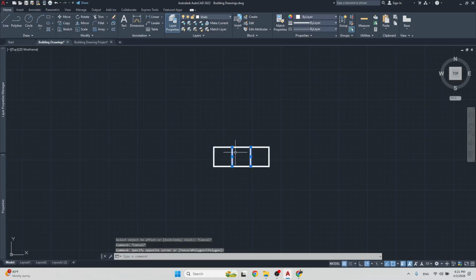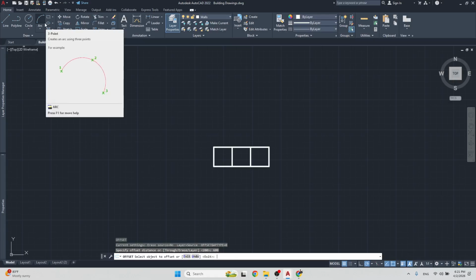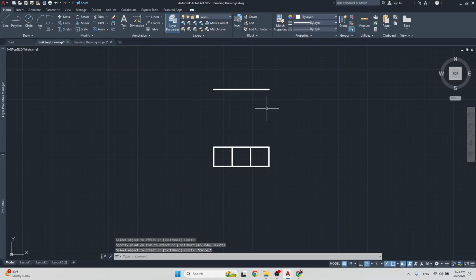And these two lines in the middle here, we're going to extend them up, and that's going to be our foundation wall. Now, something that we should also know is that the foundation, according to St. Vincent standards and maybe some other country standards also, should be buried at least 3 feet below the ground. So we're going to offset a line here, 600 millimeters. I'm going to extend it out, and this is going to be my ground line. All right, the ground level right there.